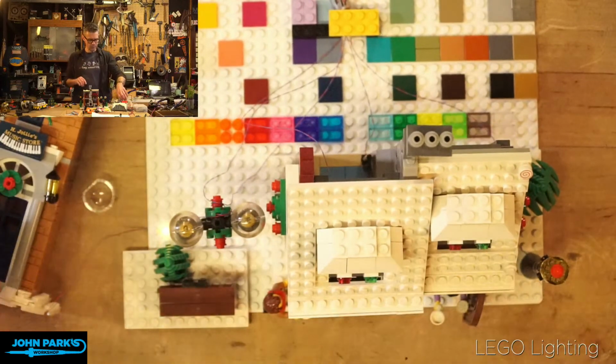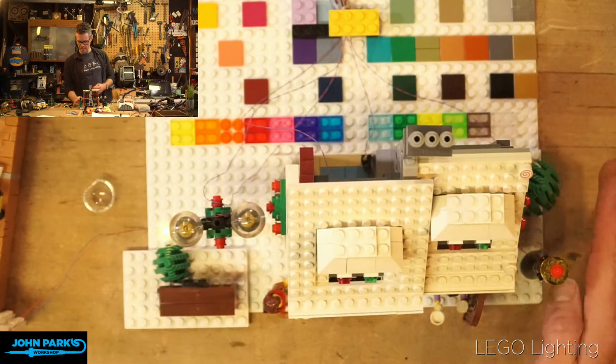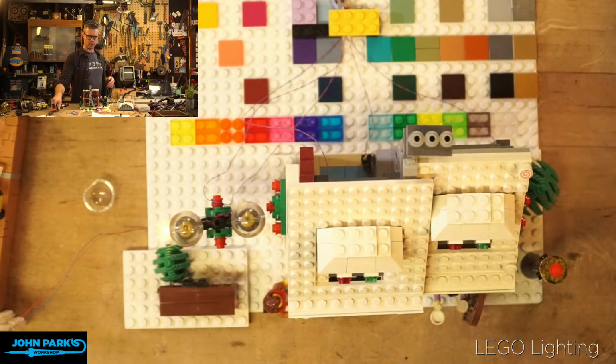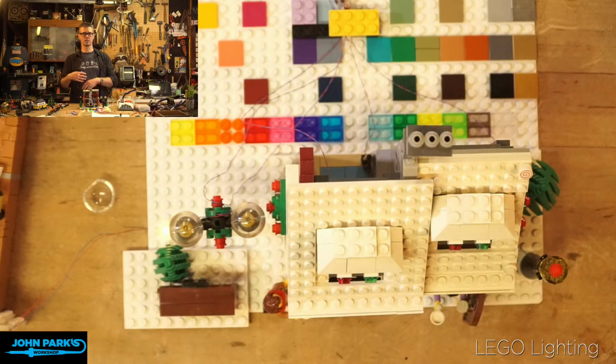So this brings us to point number 2, which is how to drive these LEDs and how to make the wiring make sense. And I think someone was making the comment, we don't really want to run these off of coin cells probably, so you could use some AA's or AAA's, but I'm going to run them through a microcontroller and an LED driver board, which means I can just run it off a USB power or a LiPo, however we want. So that opens up a lot of possibilities, including if you wanted to put things on a schedule, if you wanted things to be reactive in some way, if you wanted to put them on Adafruit I/O and make them wireless, anything is possible.